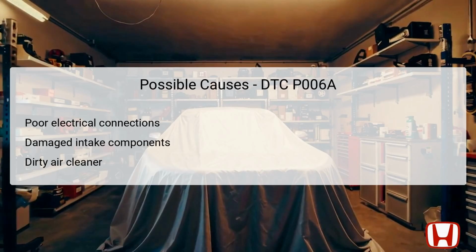Lastly, a dirty air cleaner can restrict airflow, further compounding the issue. This creates a cascade of problems that necessitates thorough inspections and checks. Identifying these possible causes allows for a systematic approach to troubleshooting, ensuring that necessary repairs yield effective results.